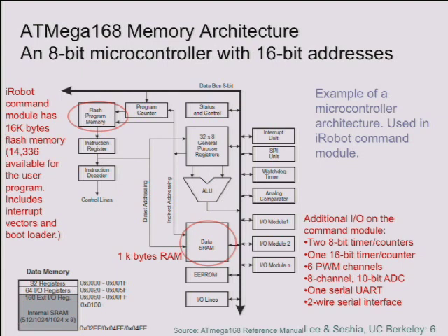I don't know. Maybe zeros, maybe garbage, maybe it'll wrap around and read some other address in memory. All of those are possibilities, right? If you use a memory address that does not correspond to a physical location, the hardware will do something. The C program will execute. It'll give you a result of the read, and what you get will depend on the hardware implementation. That's one of the things that makes debugging C programs on these processors really fun.